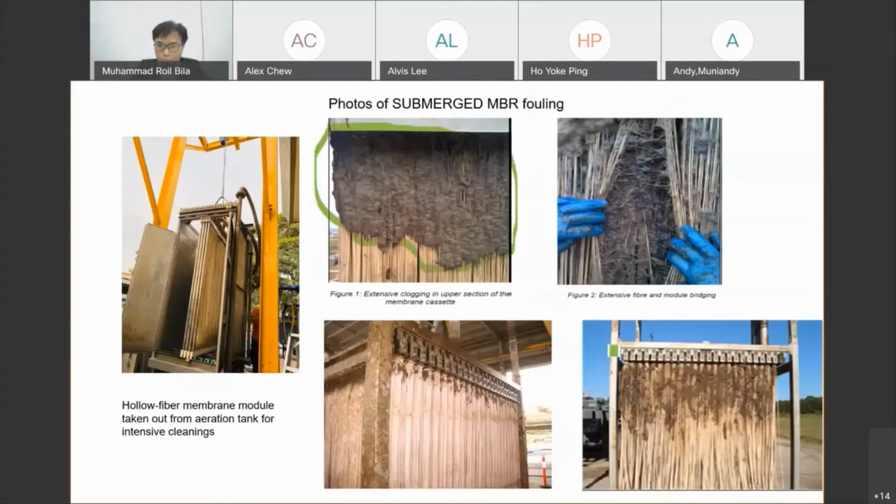So when you do aeration from the bottom here and from the bottom there, somehow the bubbles cannot travel easily around the edge. So you get a problem like this. This kind of picture is very popular in presentations of companies like Pentair or MBR Membrane that sell the cross-flow configuration.